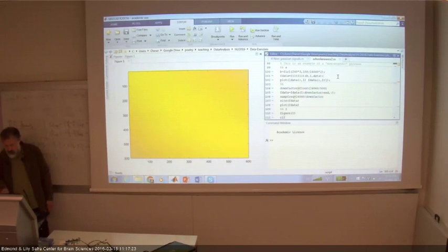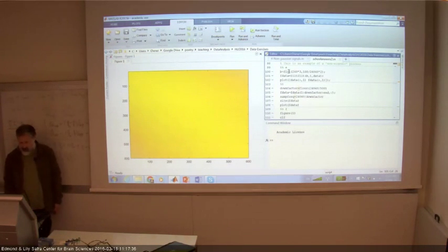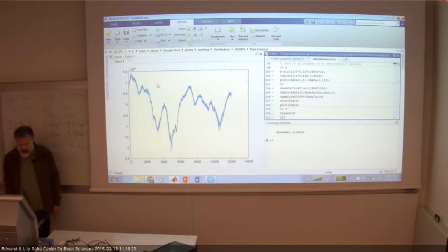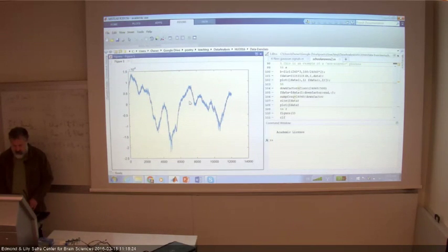Now I want to filter it and downsample. So I want to filter at 100 Hertz. Many of you tried to use FDA tool, but for this type of application, you don't need to be very finicky. I just used FIR 1 here with the same rule of thumb that I provided 2 weeks ago. So duration should be about 3 times the longest period of interest. At 100 Hertz, the longest period of interest is 240 points. So the duration is 240 times 3, and that's the corner frequency, and I filter the data. This takes a bit of time, because it's a long filter. Those of you who used FDA tool succeeded in generating filters that are at least as good as that and much shorter. But it's not very important.